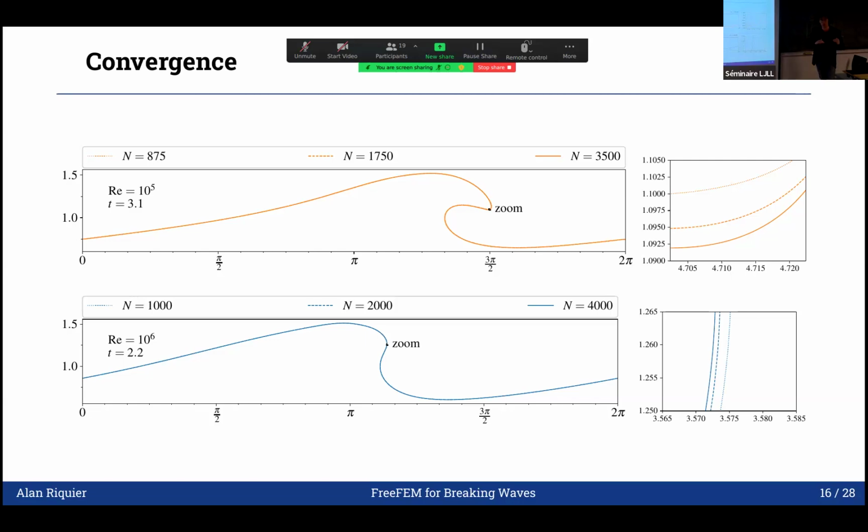But as I increase the Reynolds number to values that were never achieved before, the code becomes unstable quite quickly. So the main reason I need this many triangles, these many points, is that if I do not do so, the code will be unstable, even though it converges quite well. Of course, all this can be made quantitative using a certain distance, which I will talk about later.